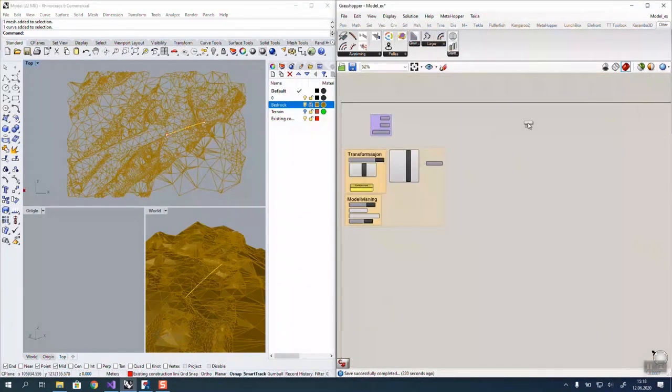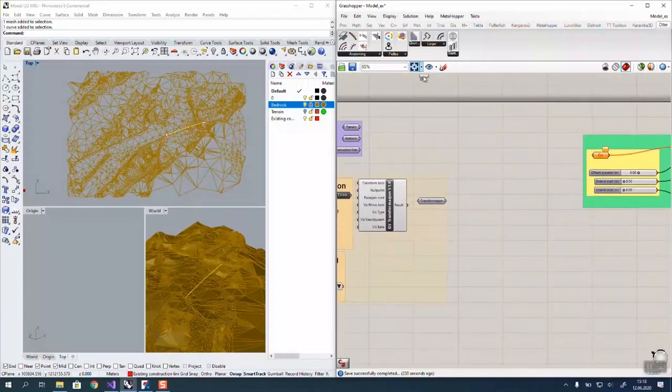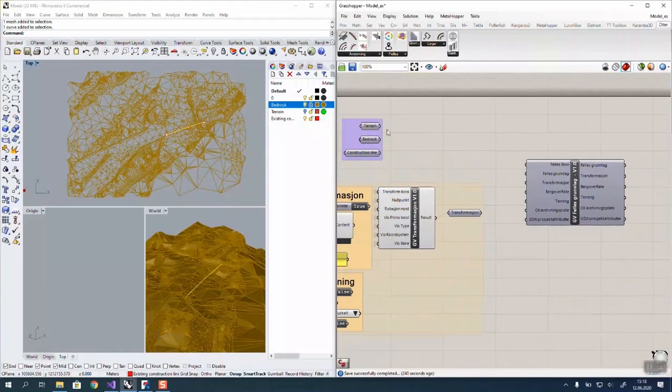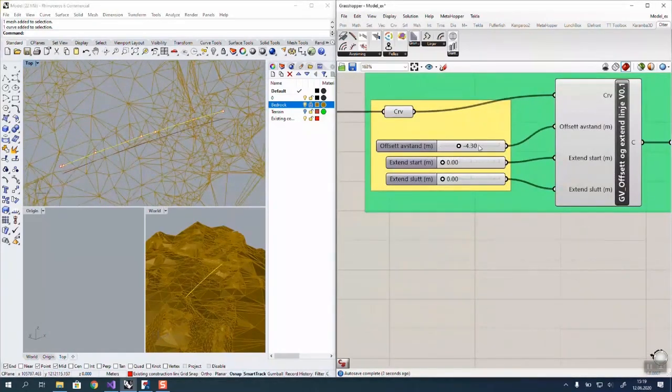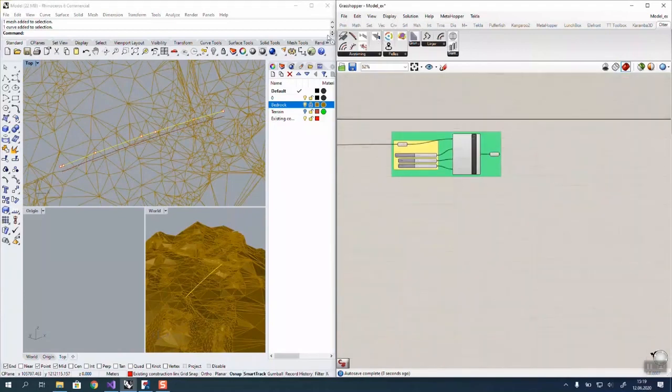The first one you see here is doing some transformations. This is due to us working in big infrastructure projects, and we used to and prefer to work in real coordinate systems. But other disciplines such as architects and structural engineers work in predefined local coordinate systems. That's why this little script automatically does the transformation between these if needed. Also Tekla works in a local system, so this transformation script will handle the transformation between Rhino and Tekla.